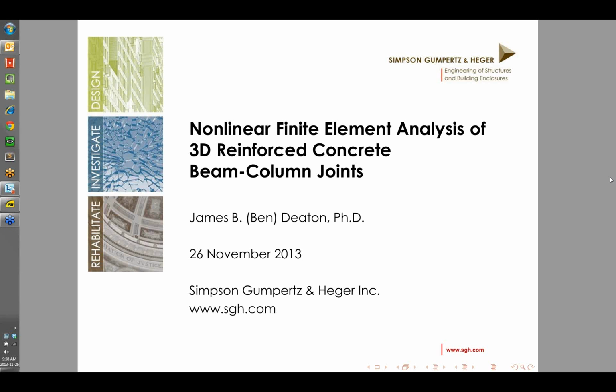I did a number of parameter studies, and initially I was curious to find out whether it would be possible just to model these with a simpler model without bond. What I found was that not including nonlinear bond slip resulted in models that were much too stiff, especially in the early cycles. So they were too stiff and too strong. For a deficient joint like this, I think it's almost required that you use bond slip.